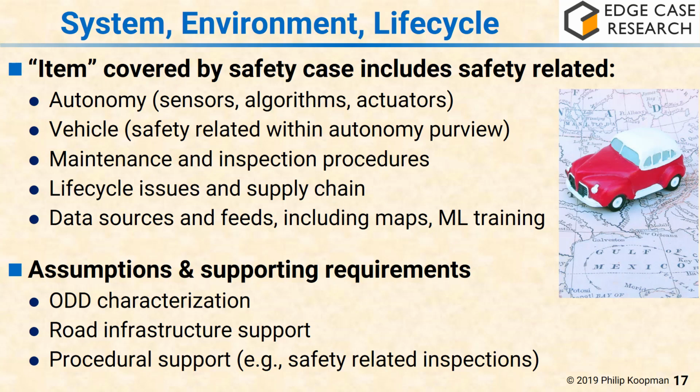You may or may not count on that, but to the degree you're counting on those lines to be painted, you have to put that in the safety case, and you have to explain what is going to happen if that's not true, or how you're going to make sure it's always true no matter what. And there may be procedural support, such as inspection procedures, maintenance procedures. And to the degree those are defined outside, that's fine, but the safety case has to define an interface and say, all right, so we're assuming the following things are going to happen some other way, and if those assumptions are violated, we're going to have a way to know that something has gone bad one way or another.